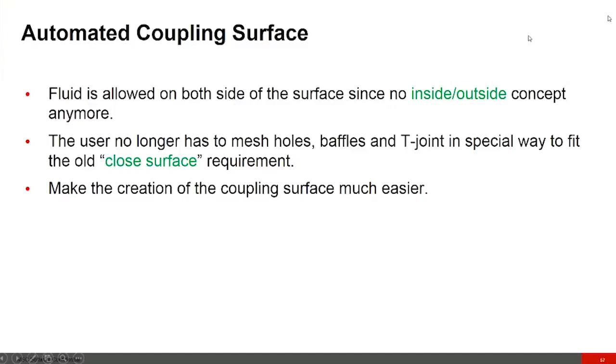With the fast coupling approach, the surfaces specified the region of the Euler domain, and this region was covered, so it was acting as a container of the fluid. Now with the new usage, the coupling surface will no longer act as a container of a fluid, but will only act as a barrier to the fluid.